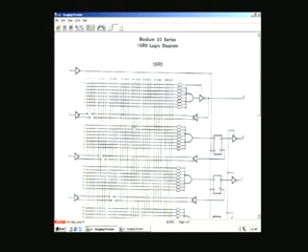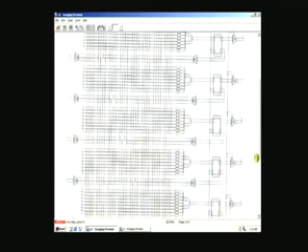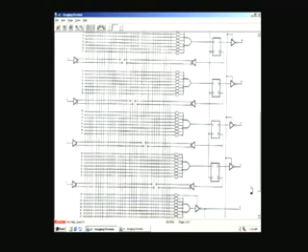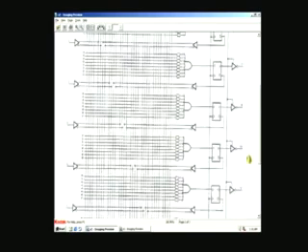CCA requires a combinational output, B plus C plus D plus E plus F. So we need a device with registered outputs as well as combinational outputs and enough inputs. One choice is the 16R6, a medium 20-series PAL which has 16 inputs and 6 registers. 16 inputs means there are 8 inputs here, and 8 inputs on this side, the left-hand side.